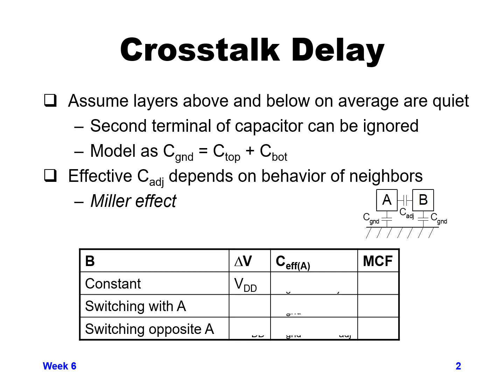Because whatever B was stayed constant, A is switching between 0 and VDD, so you have a delta V of VDD. The effective capacitance that's seen is C ground plus C adjacent, because you're going to be switching the full VDD delta between those two that are both staying constant, and the effective Miller coupling factor is just 1 because you count the entire effective capacitance C adjacent.